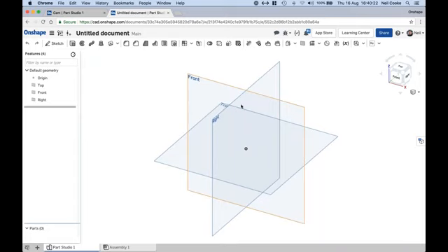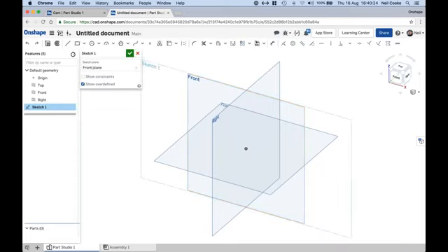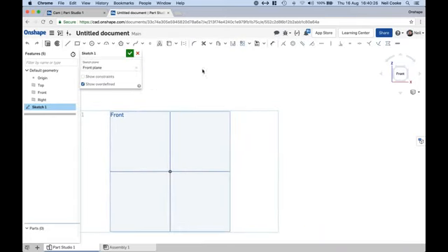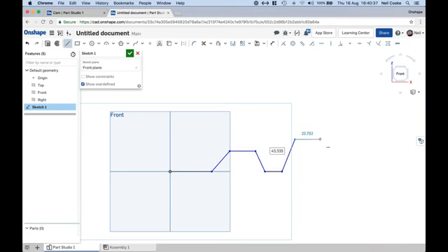Okay, so let's just do this first here. We'll start off with a new sketch, and we'll just draw in the follower position. So I might want it to stay flat, then jump up a bit, go back to flat again, perhaps jump a little higher, and then go back to flat again at the end. Now, it doesn't really matter how long these lines are, so the distance from this point to this point doesn't really matter, because it's going to be scaled to the size of the cam. What does matter though is the height.